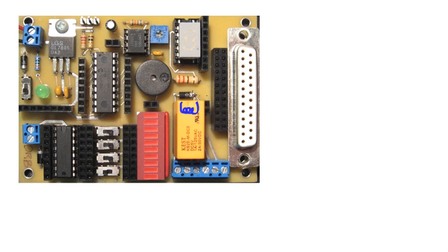Now I have in here as well a diode. That diode is to provide protection. It's a flyback diode for any counter EMF. So when the magnetic field collapses on this coil, that counter electromotive force is not going to go back and damage anything else. As a result of that, there is a specific polarity that we must observe here when making our connection. Without the diode, there would not be a need for any specific polarity. But because of that, the connection up at the top is for our positive, and at the bottom is our negative connection.